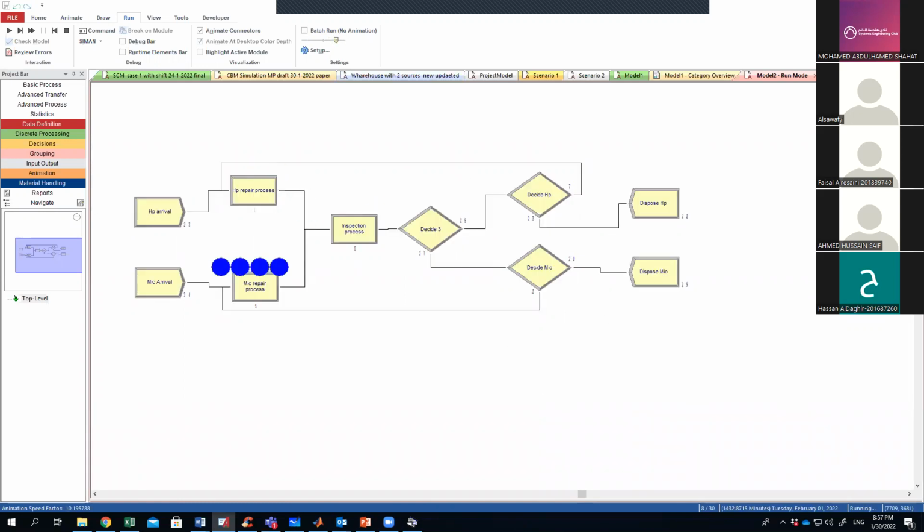If we just run it, you see here, by the way, you can track the time. Here you have a simulation clock. It will show you at what time we are now. Here the time passing is 347 minutes. And if you see here, the time is not moving continuously. Time is jumping from one time to another, and those times are nothing but the time of events. Whenever an event occurs, this is how the clock is advancing to the next time based on the time of the different events. Starting service here, finishing service from there, and so on.